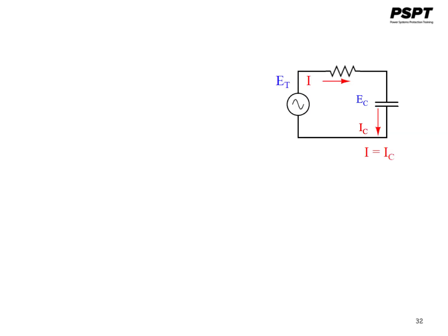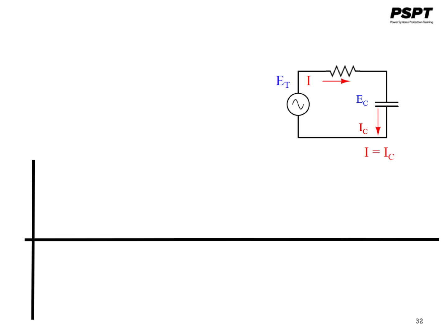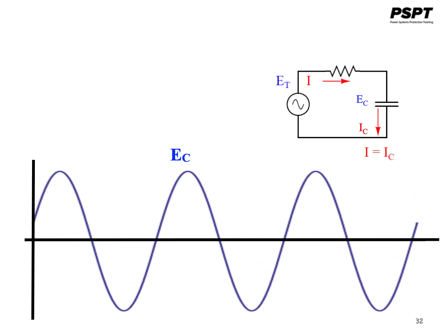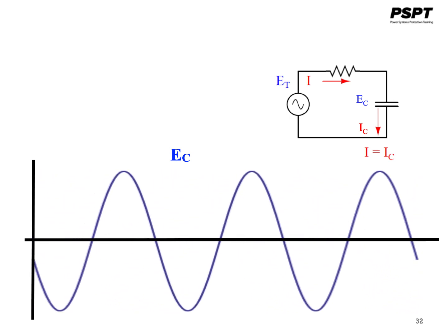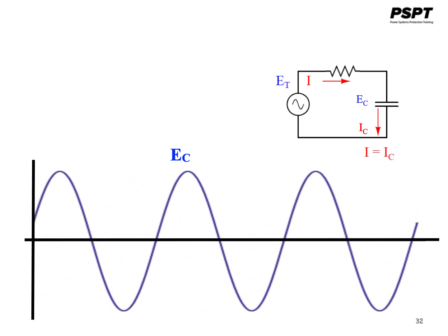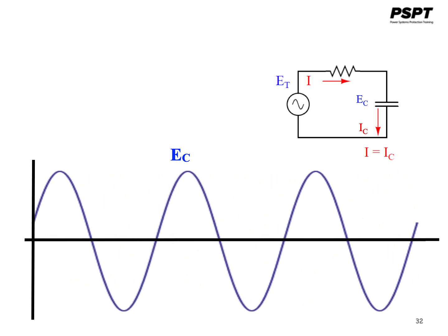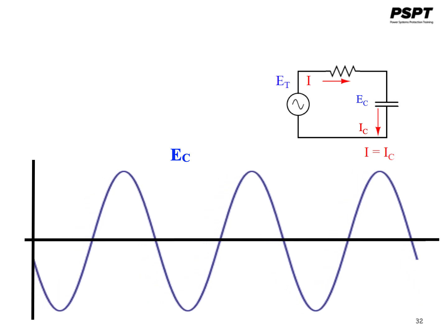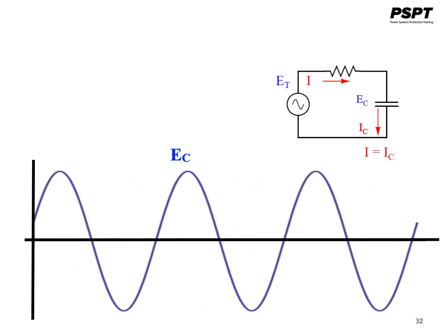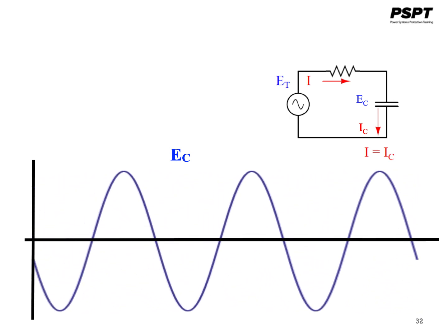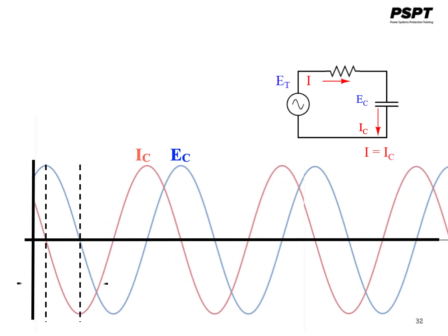The current flow in a capacitor is related to the change in the voltage of the capacitor, which is sinusoidal and always changing in magnitude, and defines the opposition to alternating current in general. The opposition to alternating current is similar to resistance, but different in that it is always resulting in a 90-degree phase shift between the current and the voltage.